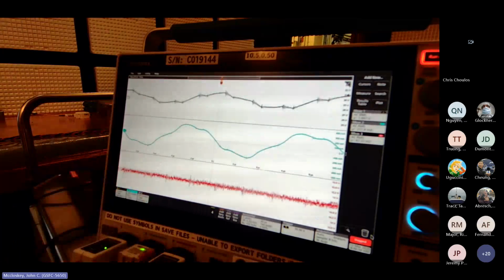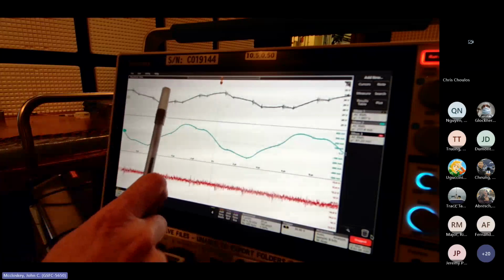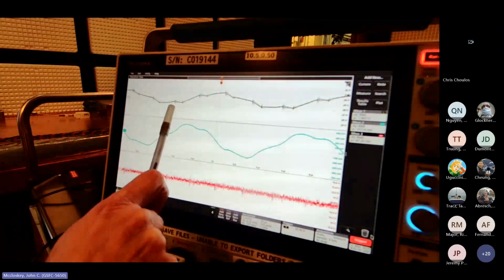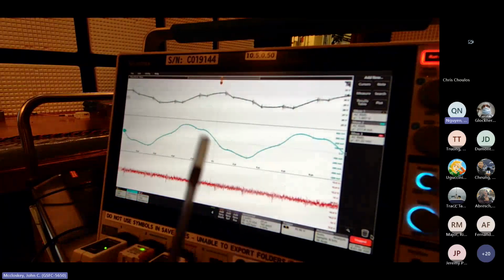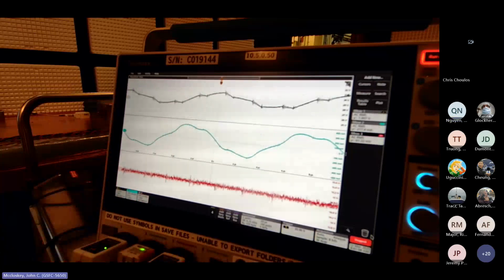These are the ringing characteristics that we saw on this waveform before we even applied a signal, our CS101 signal. So from here to here, it's about two microseconds per division. I'm just eyeballing it. The period is about 2.5 microseconds. That's our 400 kilohertz fundamental of our switching frequency of our power converter. So hey, that's what you're seeing there.